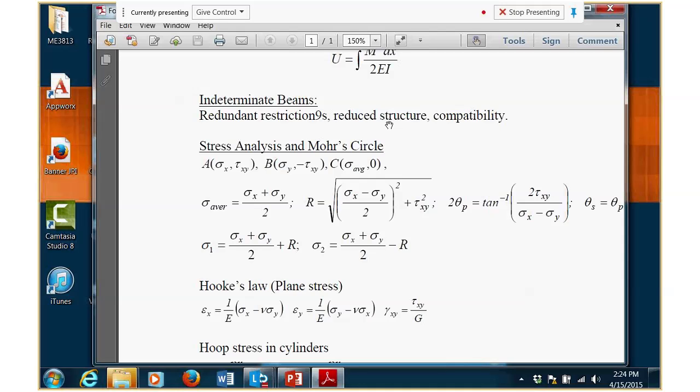And another scale you need to get familiar with is, once you have the Mohr circle, how can you find sigma 1, sigma 2, the maximum shear, and the principal direction from the Mohr circle? And that's what we just did for the cylinder, we actually just practiced it. So that's the requirement: either use the equation and calculate, or also draw the Mohr circle.